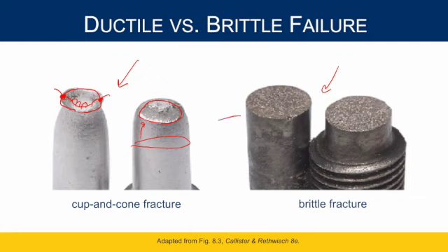This is a very hardened metal, and it has more of a ceramic type failure to it. And you will see that there's constant surface area here, constant surface area, and then it seems to just break. No warning, no change in shape or area. And if we look closer, there's a reason why this failed. If you look right here in the front, there's a little void, some kind of dimple in the side of this piston. And this is where the stresses were concentrated and where the material failed.